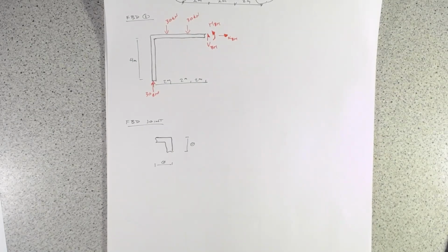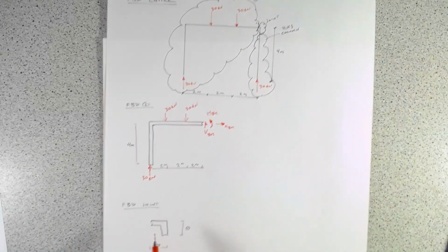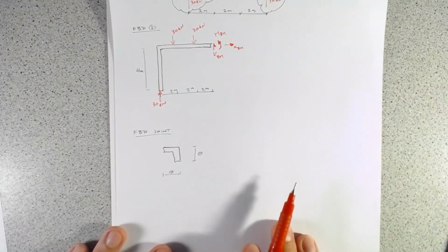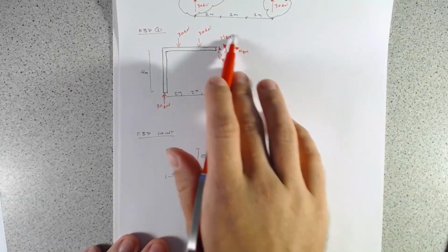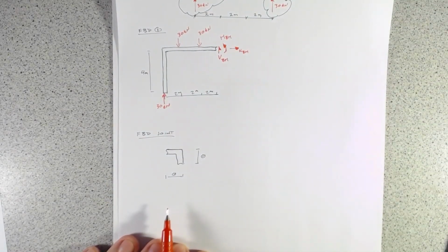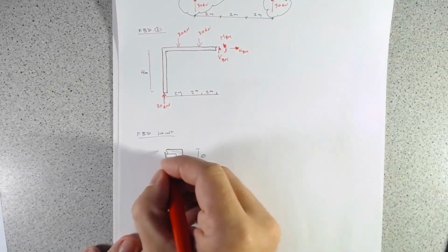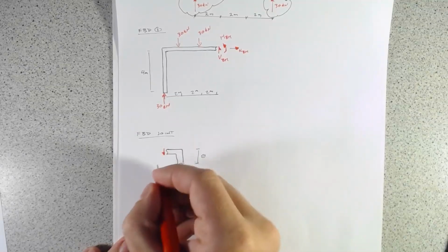And let's also, we can take this free body diagram anywhere we want. What we were trying to find here is, well, what is this moment right at the corner there? And so we're going to draw a free body diagram right at the corner. So the thing to keep in mind, again, we have 2 cuts here, so we will be exposing 2 sets of internal actions. On the beam side, they're going to be the same magnitude as what's in free body diagram 1, but going in the opposite direction. So our shear force of the beam is going up on free body diagram 1. Well, we need an equal and opposite reaction on the other side of it, so it's going to go down